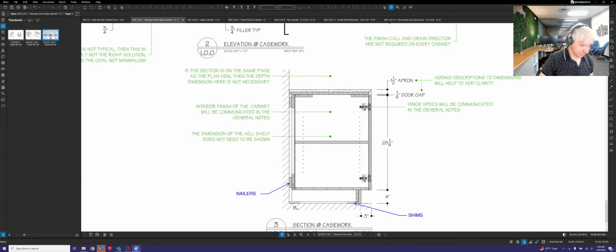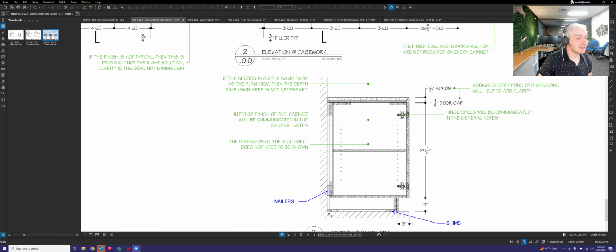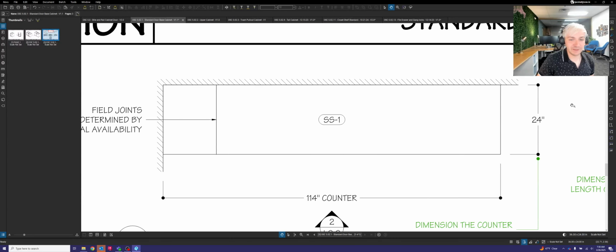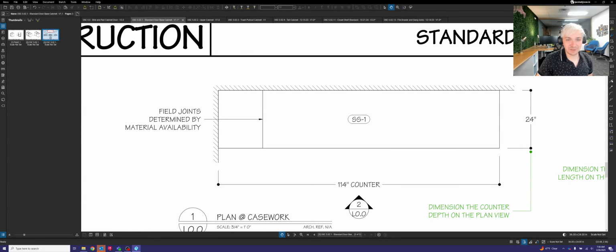Because just like the floor being unlevel, drywall does tend to be uneven as well. And so we're looking at a drywall wall that's back here behind this cabinet. And because it's drywall and sometimes they work a little too quickly when they install the drywall, it could be a little bit uneven. And so as you go and look at the plan view, it's not going to show that the drywall is uneven, but in the actual field, your drywall might actually go in and out a little bit.